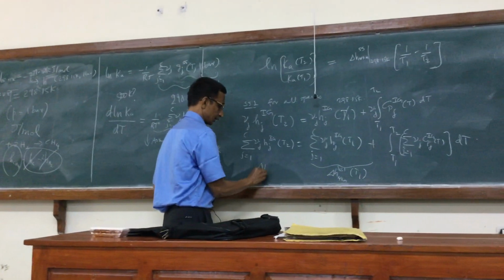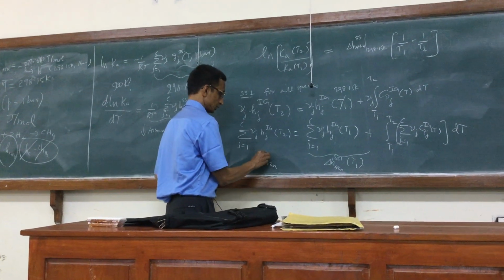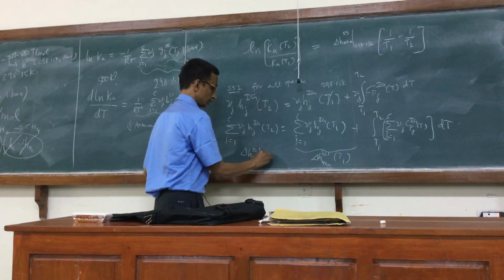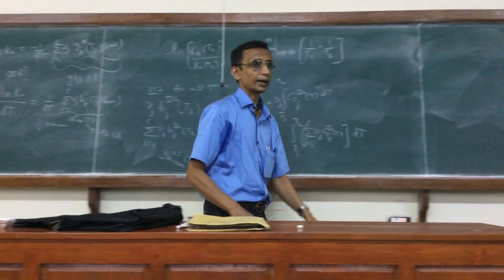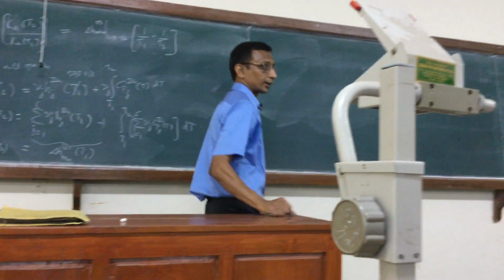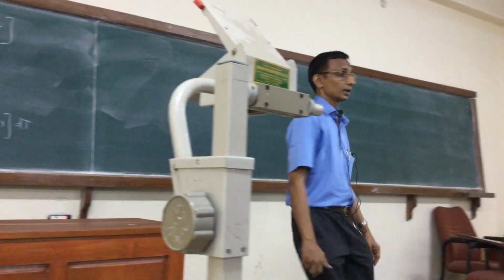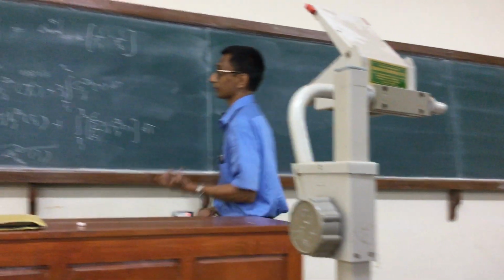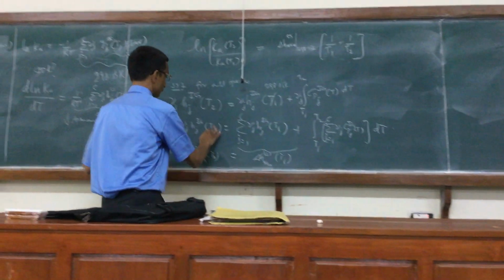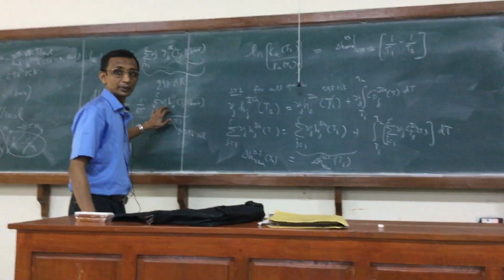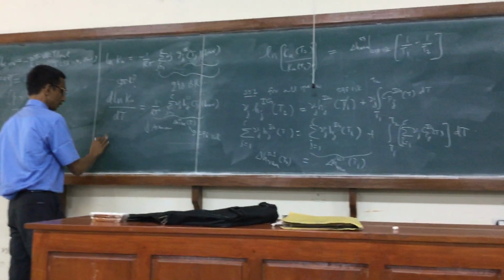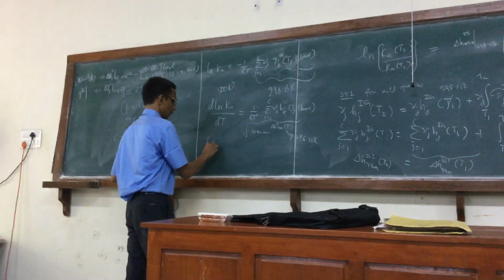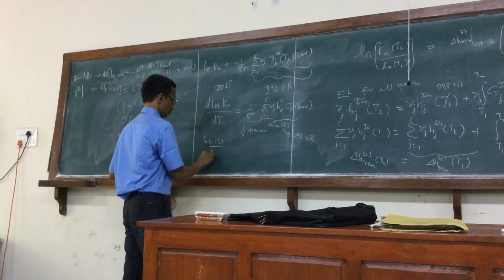So this is delta H reaction standard state 1 at T2. So given the specific heat data, I can calculate the delta H reaction. This now actually has to be expressed as a function of T because I want it at any other temperature. I want to integrate this. So this would be really log Ka of T2.